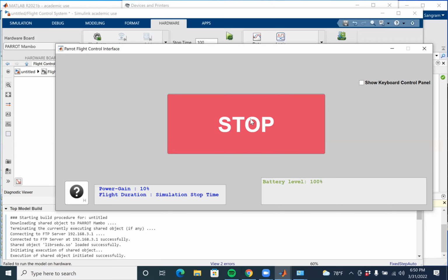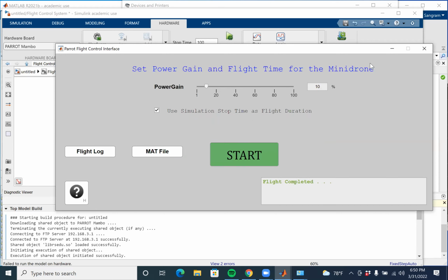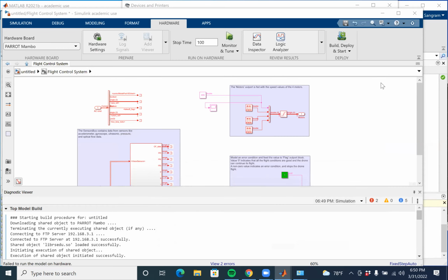We'll start step by step. So everyone, please bring your complementary filter codes. There is a different way of doing this, but I'll talk about it a little bit later. You can actually generate your own PWM and control exactly the way this PWM is generated. But generating a PWM is not a trivial task. You will need to run a triangular wave, then a comparator and all that type of stuff. So students who are in class, they're going to have all the fun.